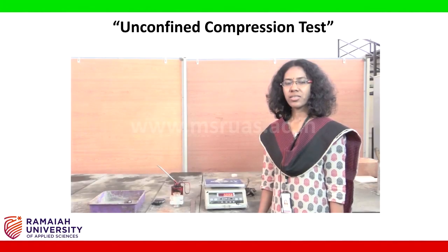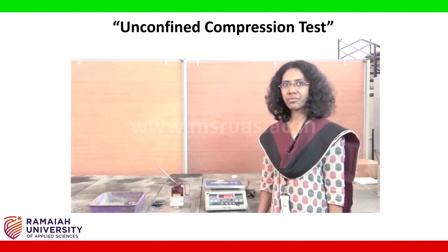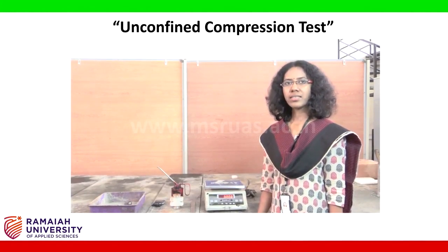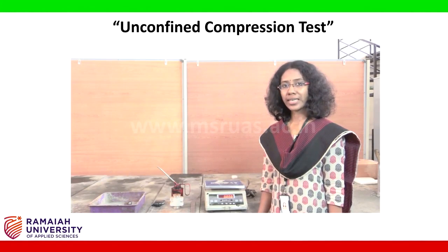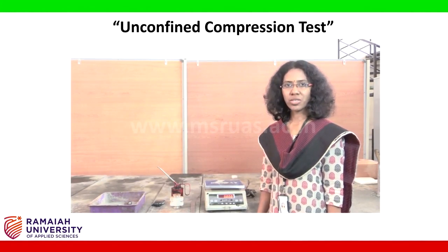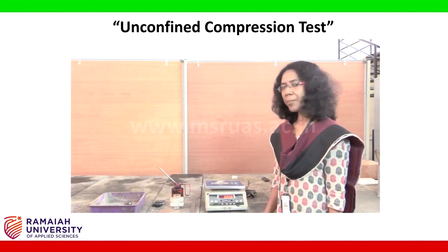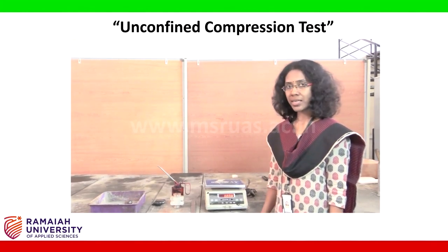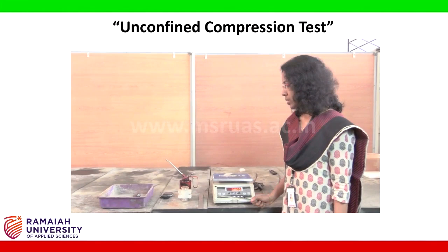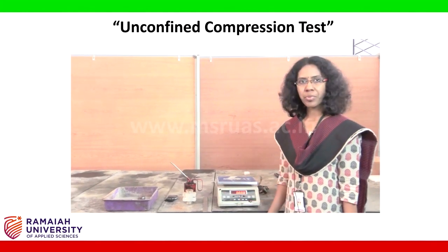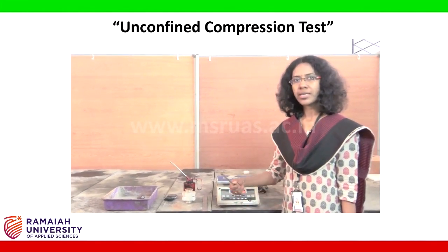Dear students, today we are going to perform the unconfined compression test. This test is being conducted on clays which can stand on their own without any lateral confinement. The apparatus required for this test can be divided into two sets: one for sample preparation and one for testing.